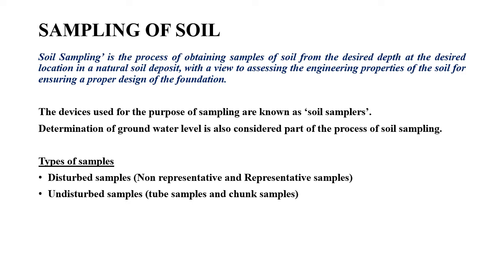And then one side of that cylinder can be sealed using wax. Now, one side of the cylinder is sealed. At the bottom of the pit, you can just insert a spatula. In this way, you will be able to retrieve the soil sample into this one-end-closed cylinder. So those are called chunk samples.